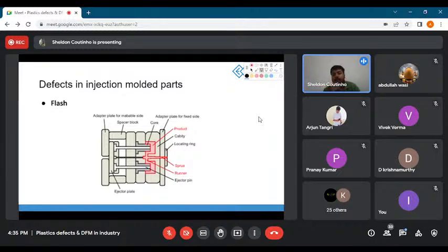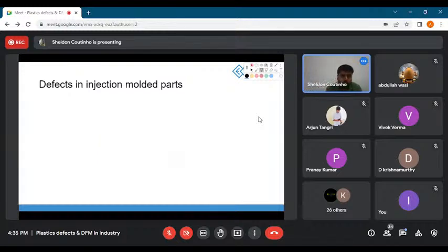Or maybe this is the last option, because if you increase the venting hole diameter, you will have plastic seeping into it, and that will cause surface deformities on the plastic as well. So the easiest thing to do would be to reduce the pressure and see if that is possible. Second easiest would be to increase the clamping pressure. Third would be to check whether it is venting out correctly or not.